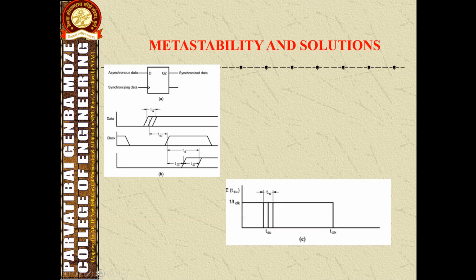Thus, under this kind of circumstance, the flip-flop enters an unstable intermediate state, which is called the metastable state. In this case, a slight deviation leads the output to revert to one of the two stable states. However, the settling time depends not only on the gain bandwidth product of the circuit but also on the original balance and the noise level of the circuit.